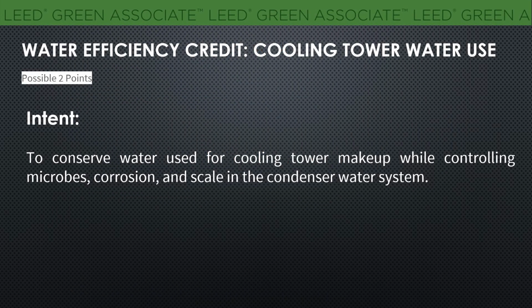Now coming to the next credit, that is cooling tower water use, and you can earn up to 2 points. The intent is to conserve water used for cooling tower makeup while controlling microbes, corrosion and scale in the condenser water system.